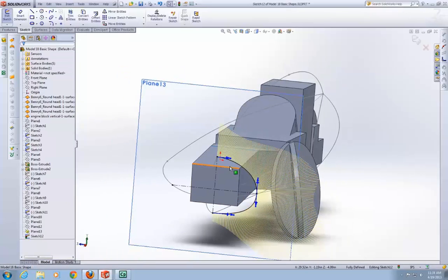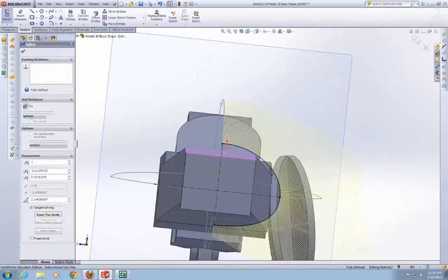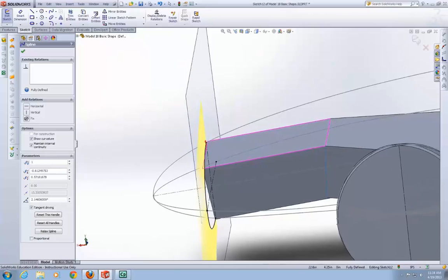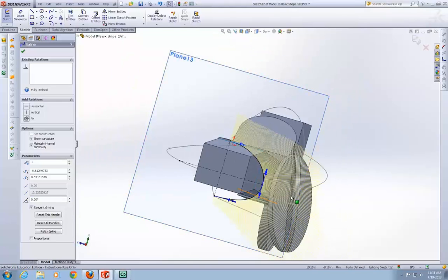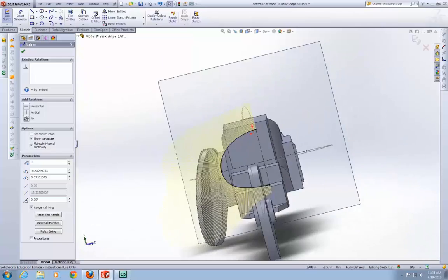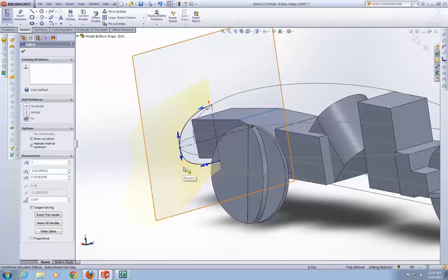See there, I delete the point. I only really need 3, and then I can define the curvature off the spline curve, if that makes sense. But anyways, as I was saying, you want those to be horizontal, and those to be so that you get a nice smooth transition between each side. That you don't get some weird ridge if you make it like pointed or something, if that makes sense.